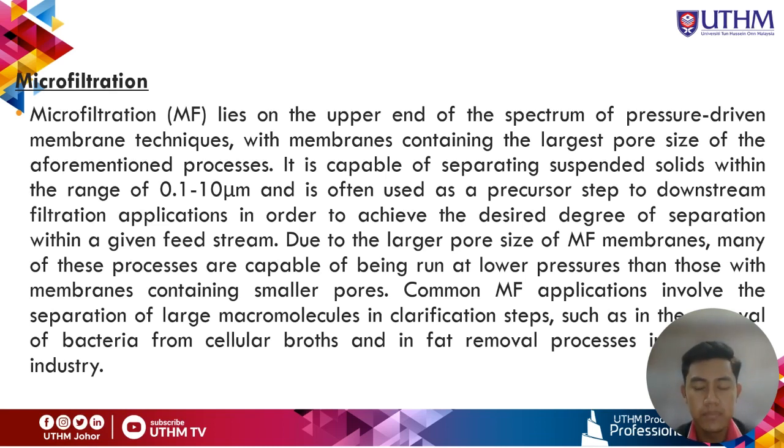Due to the larger pore size of microfiltration membranes, many of these processes are capable of being run at lower pressure than those with membranes containing smaller pores. Common microfiltration applications involve the separation of large macromolecules in clarification steps, such as in the removal of bacteria from cellular broths and in fat removal processes in the dairy industry.